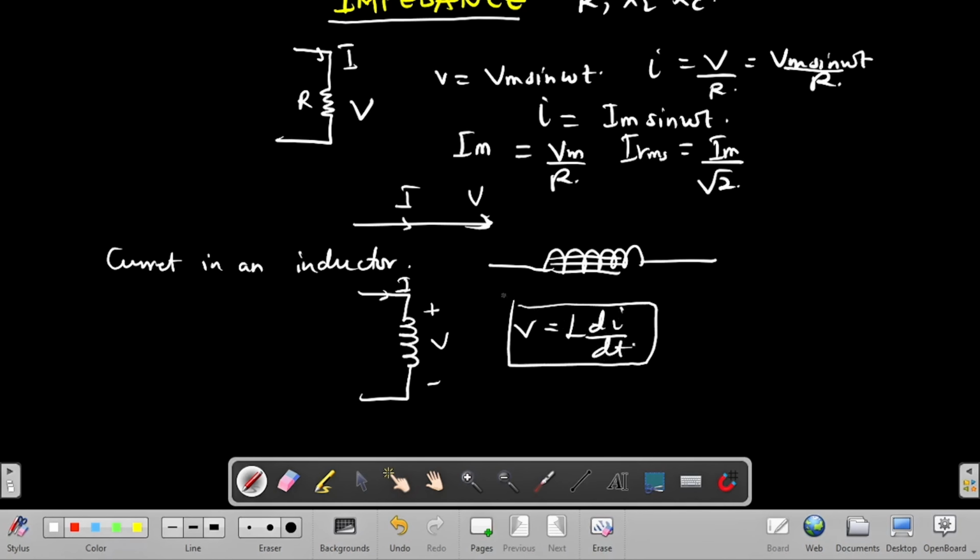So you realize that the current through an inductor is not fixed. Please take note, the change in current in an inductor, due to the alternating nature of the current, creates a magnetic field. So for us to find an instantaneous voltage, we need to differentiate with respect to the particular time we want to find the voltage. Then we multiply it by our inductance. That is all.